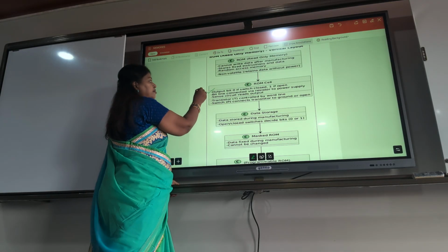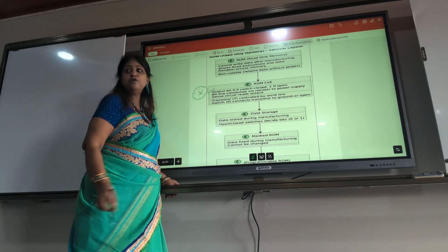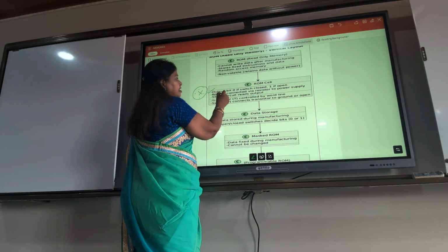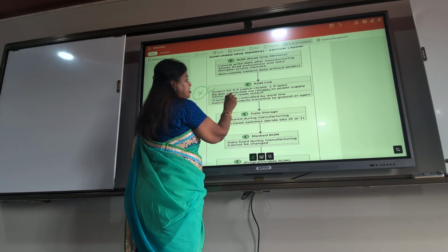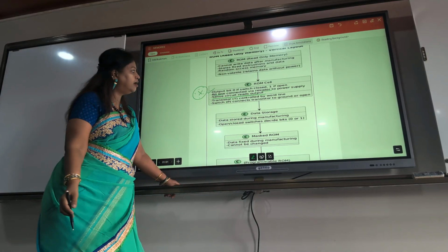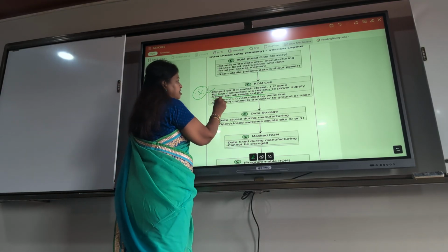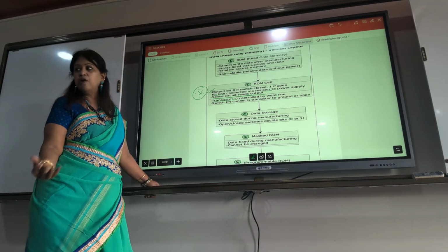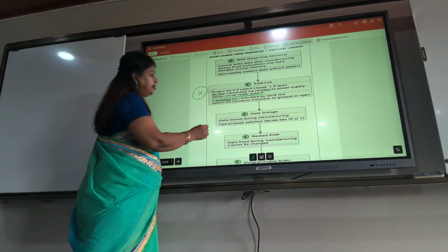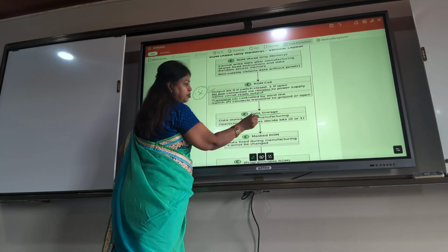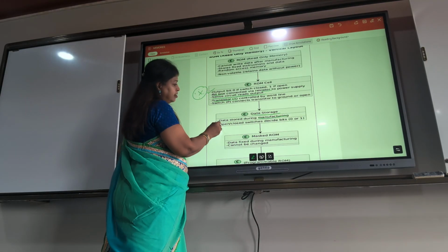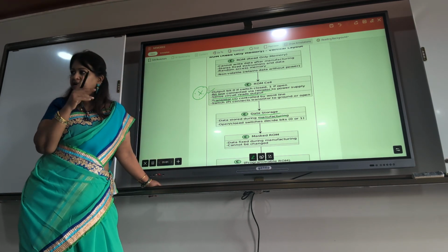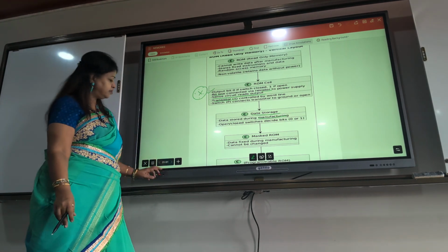This is also an important question; I will ask you to explain the ROM cell. The bit line is connected by a resistor to the power supply, since the circuit reads the output. Transistor P is controlled by the word line, and the switch connects the transistor to ground or output. The data is stored during manufacturing. When the switch is open or closed, it decides the bit, 0 or 1. When you open, it is 1; when you close, it is 0.